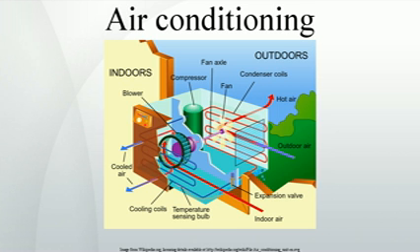Some of the sensible heat of the entering air is converted to latent heat by the evaporation of water in the wet cooler pads. If the entering air is dry enough, the results can be quite cooling. Evaporative coolers tend to feel as if they are not working during times of high humidity, when there is not much dry air with which the coolers can work to make the air as cool as possible for dwelling occupants.